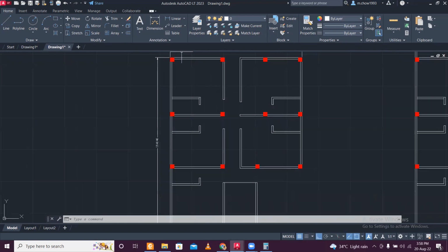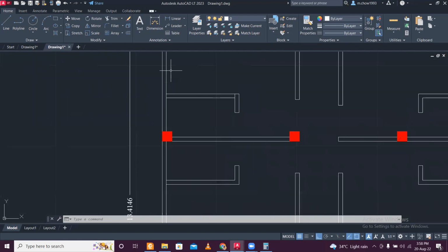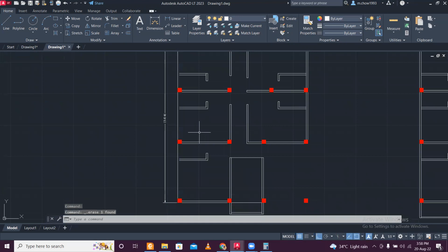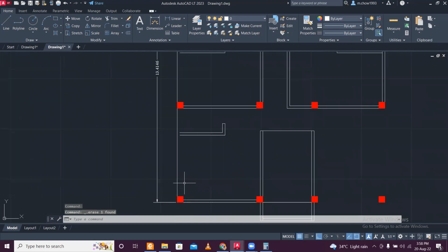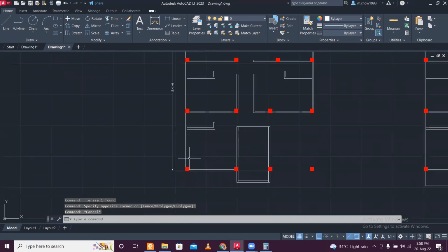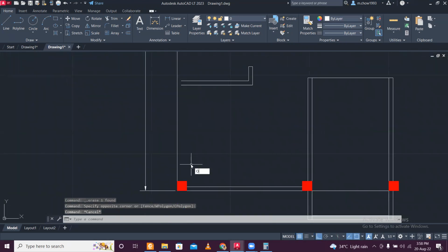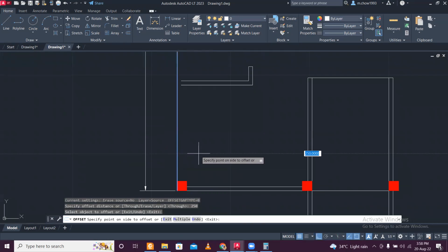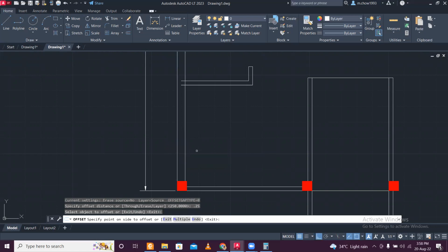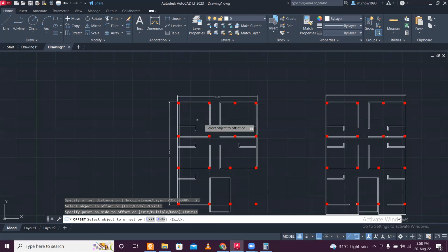First of all, let us make our beam column plan here. So first of all, let me just delete this, right? So the beam will be, this is a solid line here. So the beam will be a 250 mm beam, which we'll take for the plinth, obviously 250 mm beams, and this will be 250 mm. Sorry, it will be in meters, I forgot the meter. 0.25 it will be. So 0.25 from here is the size.